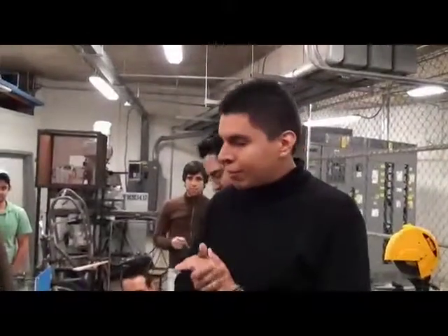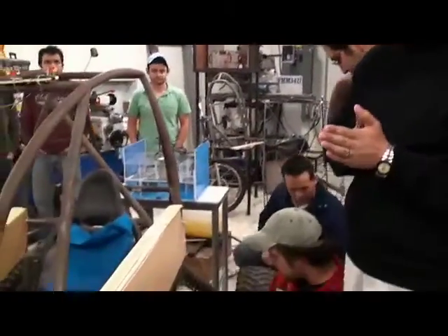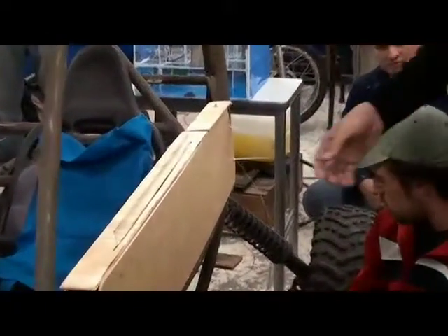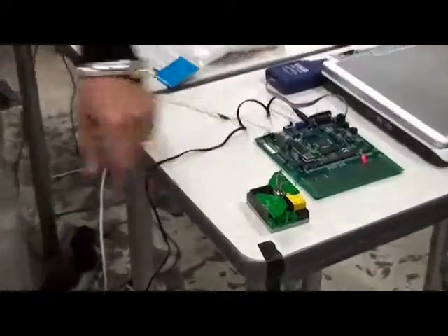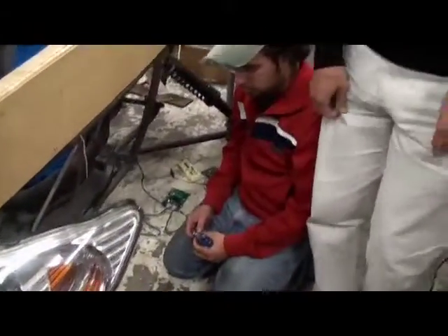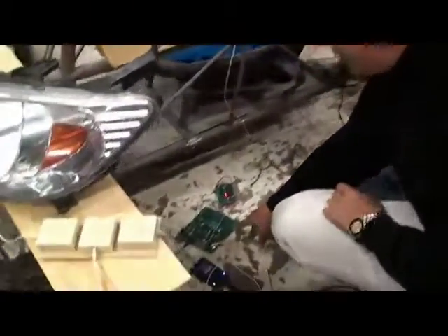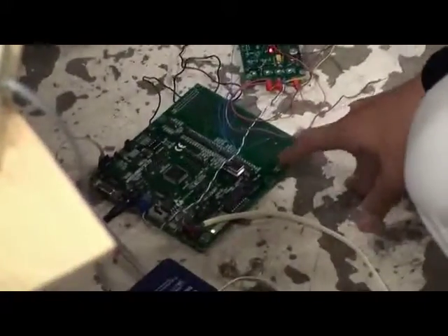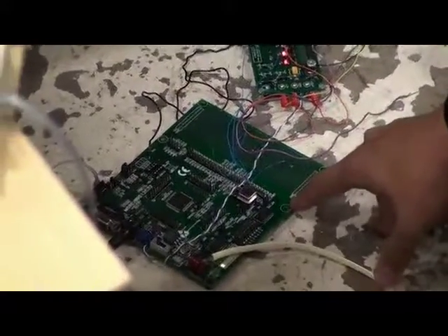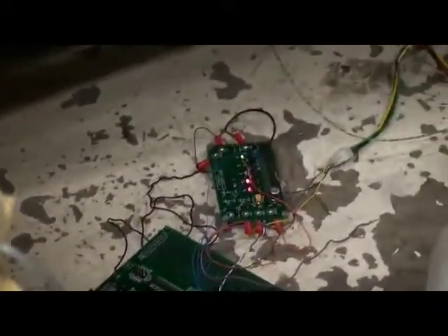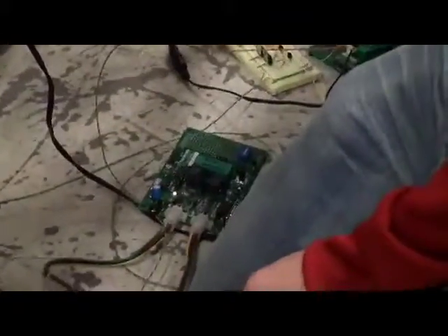Okay, we are the part of the team assigned to the doors in this car. Well, our circuit functions the following way. From the ignition key, we receive a signal that goes through CAN to our MCU. There in the MCU, it has programmed a master card. This master card manipulates two slave cards. Each of these slave cards is for one of the doors.